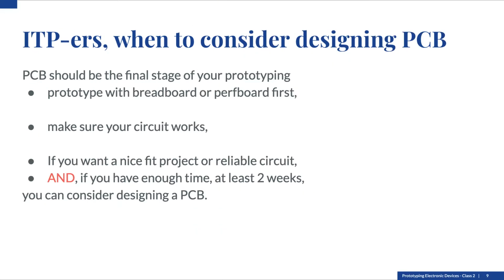For an ITP project, when should we start to consider designing a PCB? PCB should be the final stage of your prototyping because it takes some time to fabricate. You can prototype with a breadboard and proof board first in order to make sure the circuit works. And if you want a nicely fit project or reliable circuit, and if you have enough time, at least 2 weeks, you can consider designing a PCB for your project.